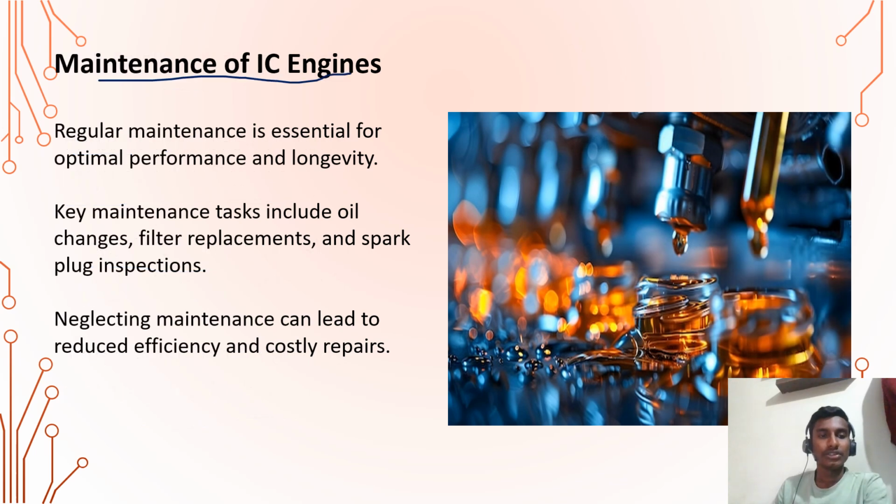Maintenance of IC engines. Regular maintenance is essential for optimal performance and longevity. Key maintenance tasks include oil changes, that is for lubrication, so that there is no wear and tear in the components, filter replacements so that the air cooling does its proper working, and spark plug inspection so that there is no problem in the starting of the car. Neglecting maintenance can lead to reduced efficiency and costly repairs.